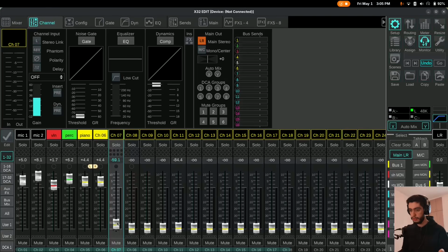And now guess what? When I turn up that fader, I can expect to be able to turn it up all the way to 0 and nothing terrible happens. I can even expect to turn it up to plus 10 and nothing bad happens. Why? Because I already set the level of the speakers. They cannot go any louder. I'm not leaving them on full volume because modern speakers are way overpowered. They are way too loud for almost any scenario if you just leave them at full volume.